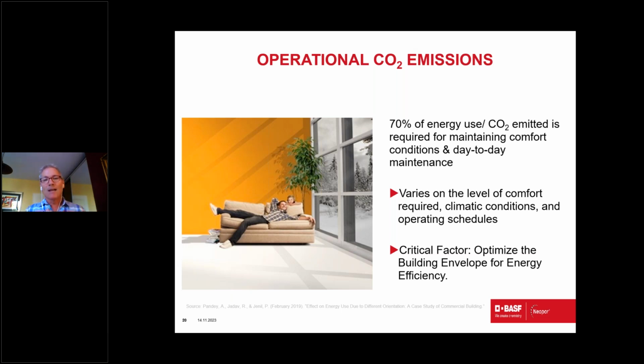Thinking about electricity, in order to get that kilowatt of electricity to your building to be able to use, you've already kind of lost 2/3 of it before it ever got to you. So in other words, every kilowatt that we use in a building, I had to make 3 kilowatts to start with. So the coal power plant, the solar power plant, the wind power plant, whatever that was, usually those are only 30 or 40% efficient. So you lose 60% of everything you put in before you get going.